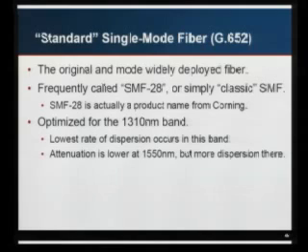So standard single mode fiber is the original fiber that was most widely deployed, in the early 90s. It's called SMF-28. SMF-28 is actually a product name from Corning. It just happened to be the fiber at the time that most people deployed. The proper term for it, you can just call it classic, standard single mode, or you can call it non-dispersion shifted fiber. It's covered by the G.652 standard, and it's optimized for 1310.